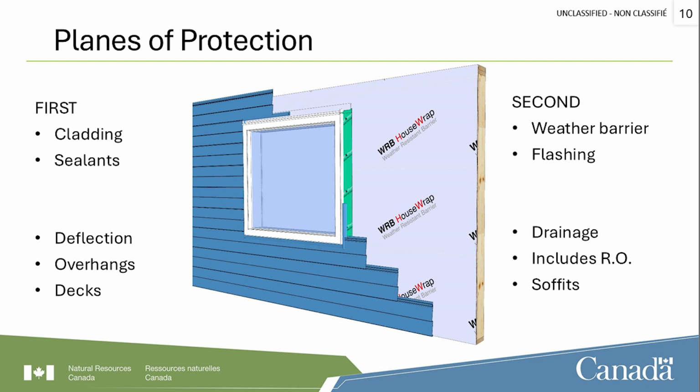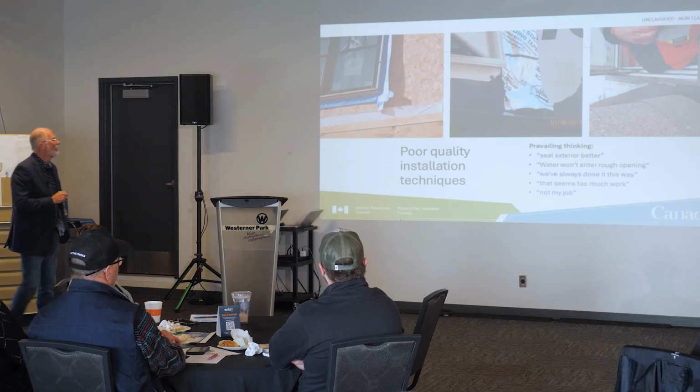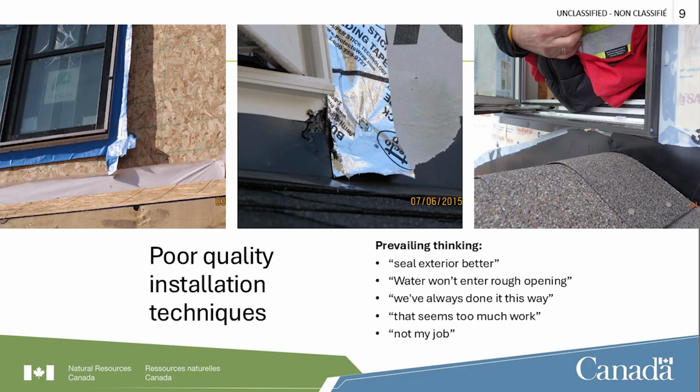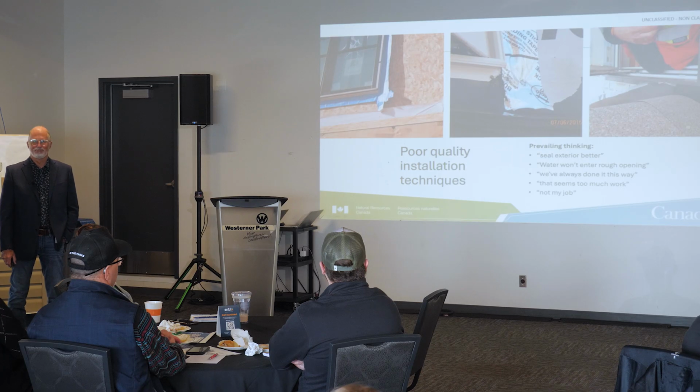Mark. Thanks. Could you go back one slide? Yep. I love the picture on the right because that shows how much the designer matters as well. You can't design a window in that location and then just fault the trades when it doesn't go well. Right? You got to set the trades up on site for success. And that comes with leaving enough room around these openings to properly detail and work. That's just a detail that's not going to go well. It's a design concern as much as it's a materials and install concern, even more so perhaps.